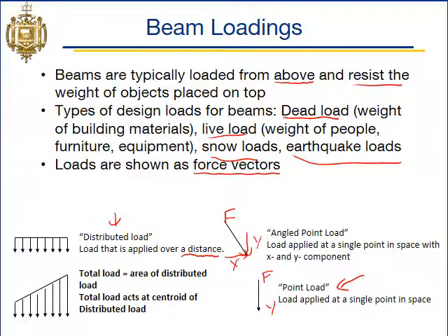Knowing the weight and size of those tiles, we say this particular tile, by applying to the floor, is going to apply a distributed load of X magnitude over the length of the floor. So we'd model those as distributed loads. Distributed loads have units of force per length, so pounds per foot, potentially.